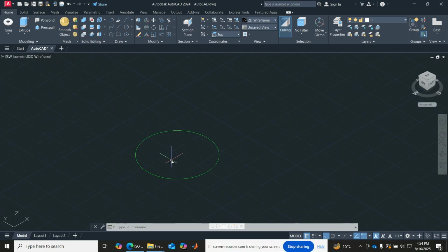So now I have to draw the feature that I want to loft to. I have to draw it perpendicular to that previous feature. So I have a circle here. Let me draw three circles of different diameter here. The second diameter can be half, and then the third can be the same as the one downward. And you see what lofting does.